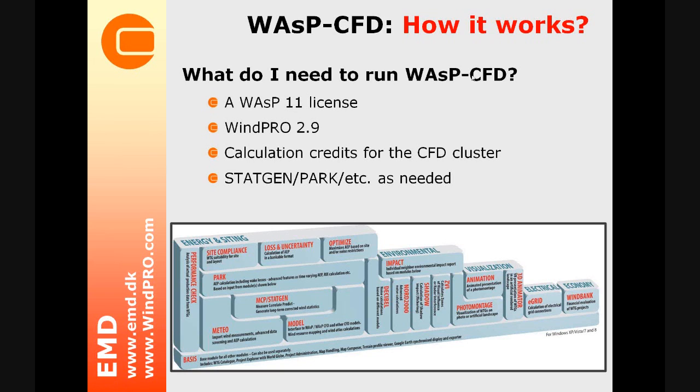Then you'll need to have some calculation credits for the CFD cluster, and also you'll need to have access to some of the energy modules where you can consume these CFD flow results. And actually most of the energy modules in WindPRO that we have down here on the screen will be able to consume the WAsP-CFD flow results.